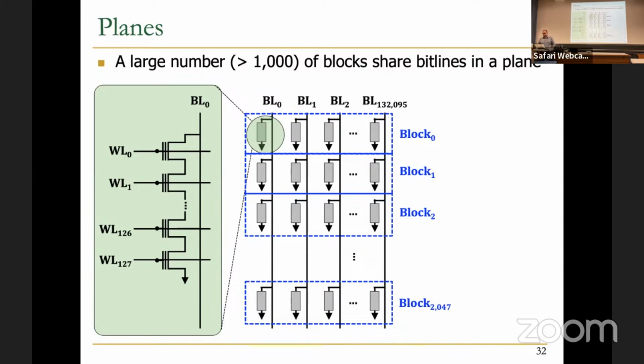So normally in QLC, when you write, you actually write to the whole page. In QLC, you can consider that each word line stores 4 pages. And that's why you need to have data for the whole pages, and then you can program QLC. So you don't really program only one bit of that QLC. Is that correct, Rakesh? For QLC, we need to program 4 pages at the same time, right?